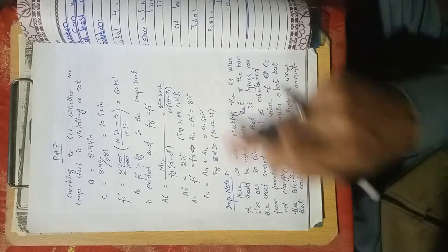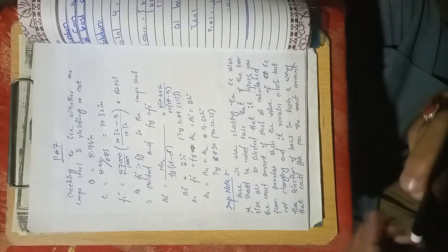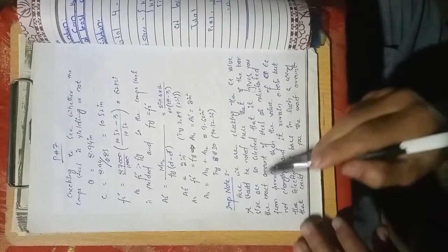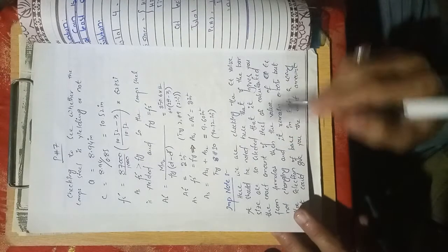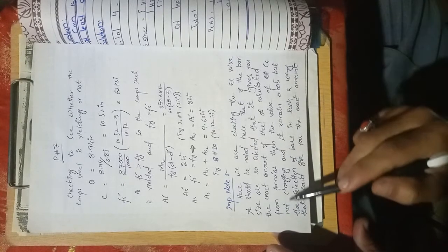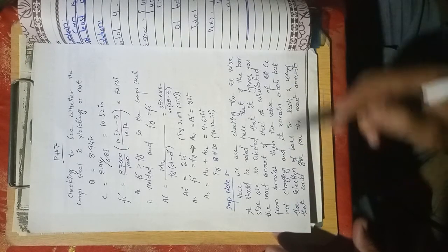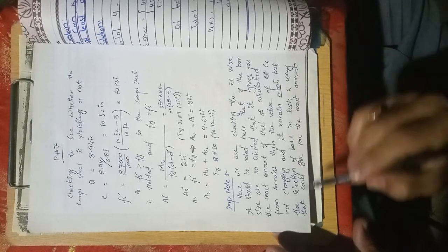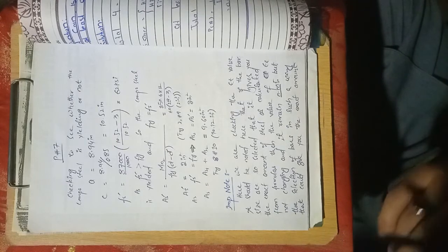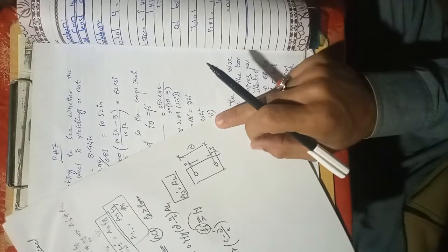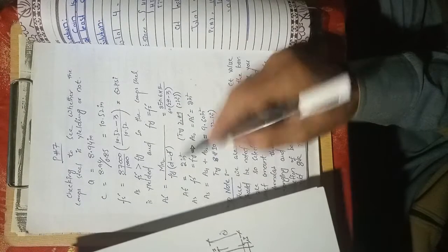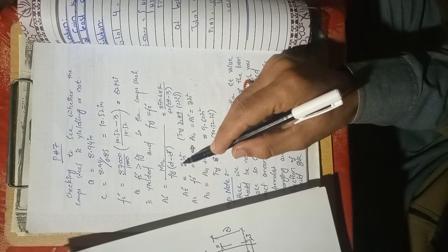Now, an important note. Here we are checking the epsilon t value. It should be noted that if the bar sizes are selected so that they give exactly the amount of steel calculated from the formula, then the value of epsilon t does not change and remains 0.005. In this case, we are using 2 number 9 bars, which give exactly the reinforcement we theoretically needed.